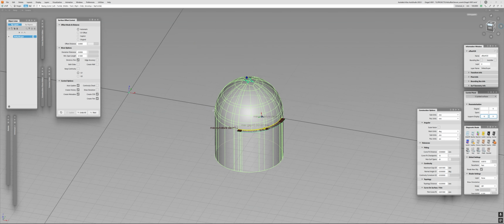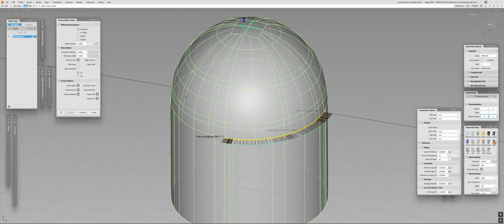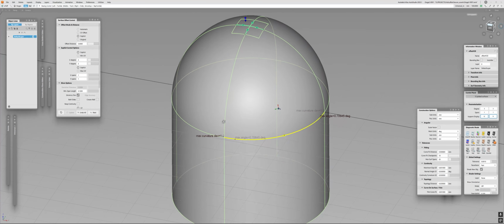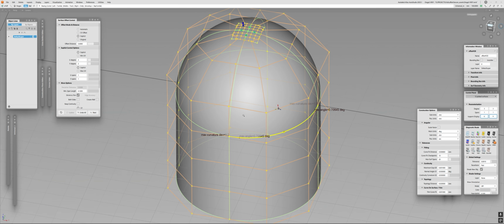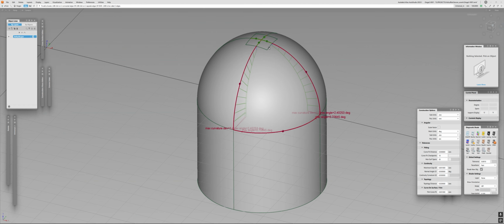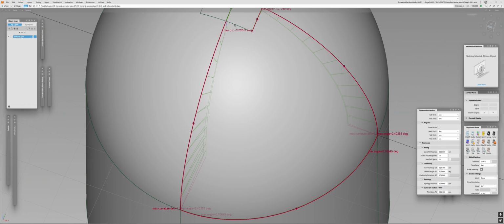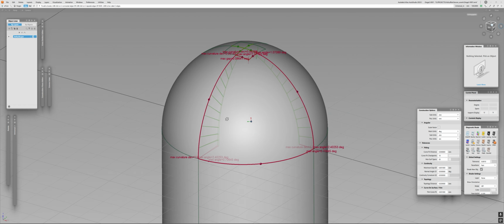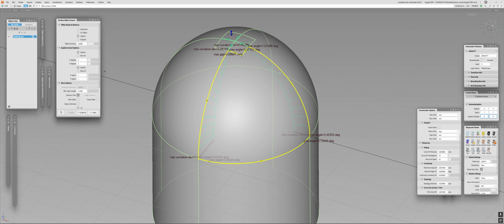So what are you going to do? Well, as we already discussed with the periodic things, CV offset will not really work very well. So let's go straight into the explicit. And even with the surfaces of 3x3, let me just check this. Oops, zoom in. Okay, so even with the 3x3, you're going to see that we eliminated the deviation here. Now we have a deviation here. Okay, let's try to increase a little bit more. Maybe 5, maybe 5 more. Okay, at this point, I'll probably just stop.